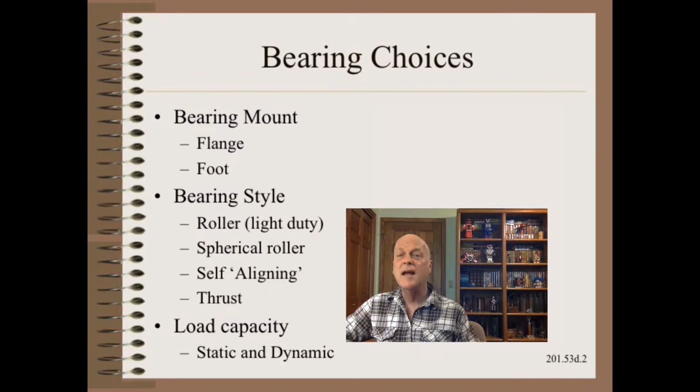This is caused because non-cylindricity of either roller causes the system to act like a cone drive. Perhaps surprisingly, maximum loads do not depend on the size of the cylindricity error, only on its shape. Pure tapers can reach near mu N, while very narrow and random diameter errors will cause little thrusting.